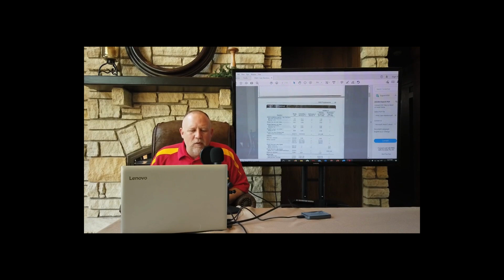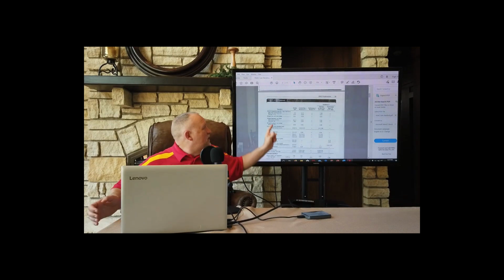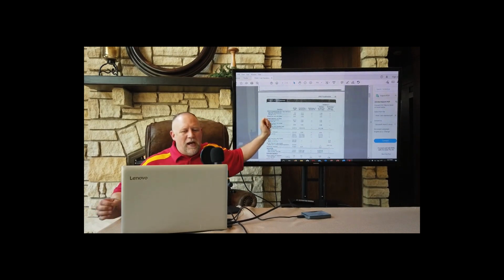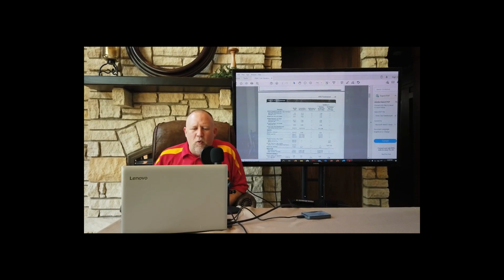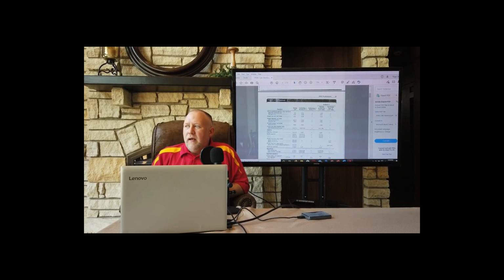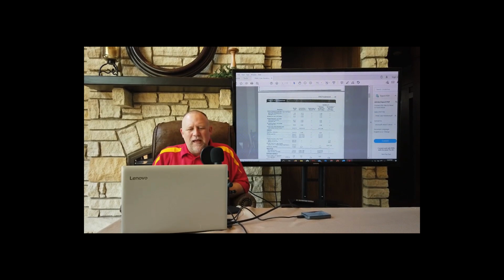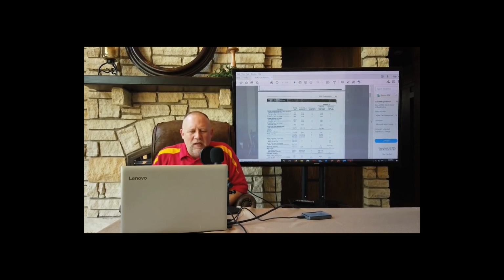Roofing. A common roofing insulation is this one, cellular polyisocyanurate. It has a good R value, but also it's more durable. In other words, we're worried about people walking on it for a low-sloped roof, or perhaps hail and wind and that type of thing. So common roofing insulation is that polyisocyanurate.